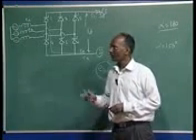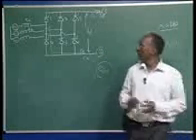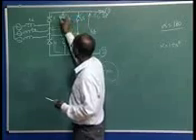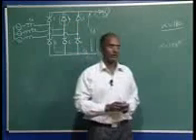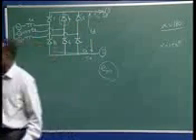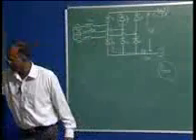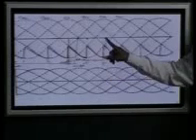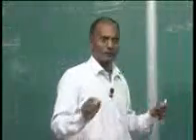Now I want to draw the valve voltage. Here let us suppose I want to draw the valve 3 voltage, again on the same plane. Here I will also draw here, because the voltage will come on that, so it will be clearly visual. Now you can see once valve 3 is fired, we can start from here. The voltage across this will be 0, and it is continuing up to here, because each valve is conducting for 120 degree.